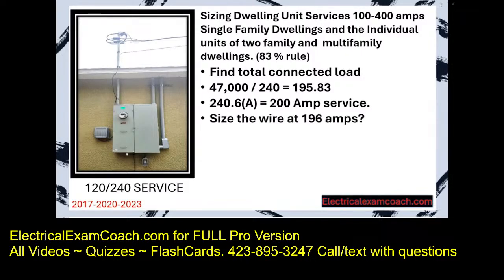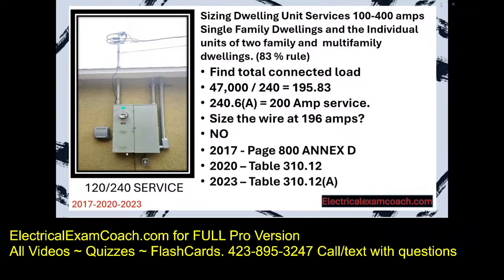Now the next step normally would be to size the wire at 196 amps, right? That's our known load. We can just follow our normal ampacity rules. Well, not with services that are in between 1 and 400 amps. And let me show you what I mean. Let's all head to page 800 if you're in the 17, this table if you're in the 20, and this table if you're in the 2023. This is technically called the 83% rule, but I'm not going to force you to do the longhand math. I'm going to take you to these tables that are in the NEC that are almost like a cheat sheet that makes this super easy to apply and understand.